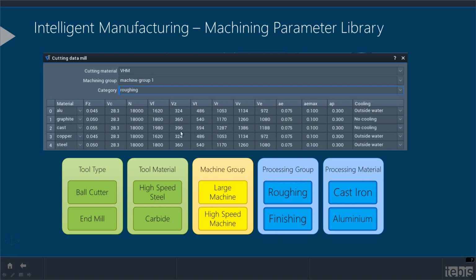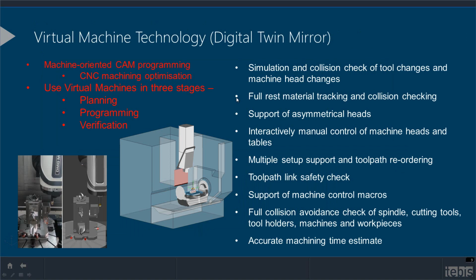with our technology for things like step over feed rates, our plunging feed rates, cornering feed rates, and plunging feed rates. That together with our optimal step overs with the AE values and our optimum step downs or depth of cuts with our AP values. Not forgetting the cooling option for that particular material that should be applied. So very, very advanced cutting conditions within the Tebis software.